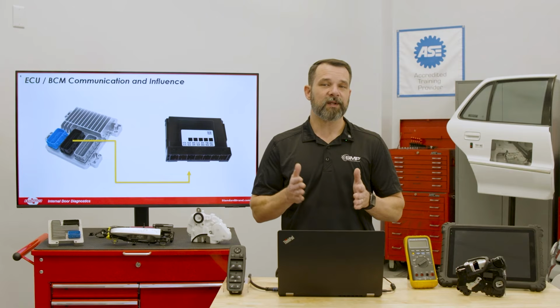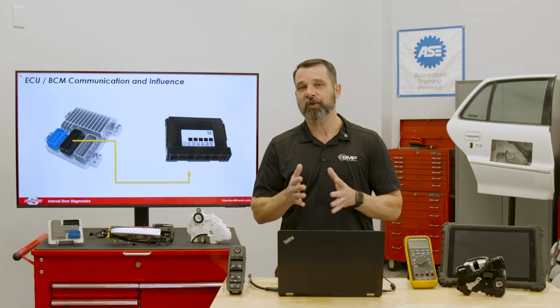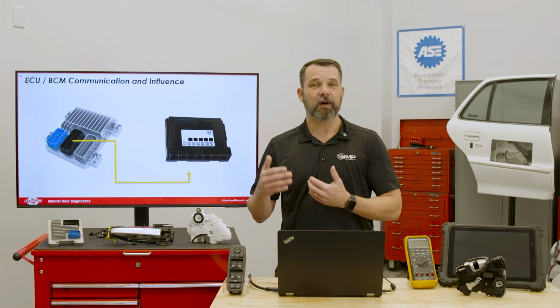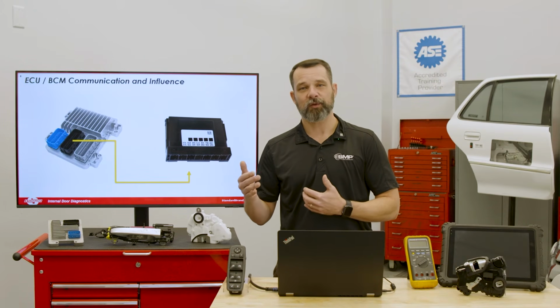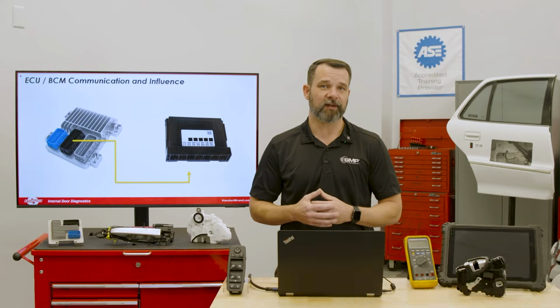Now, we also have the security immobilizer authorization going on between the two at all times. The ECU and the BCM are exchanging encrypted data, and the BCM often will not unlock or power certain circuits if the ECU reports an unauthorized key or something like that.